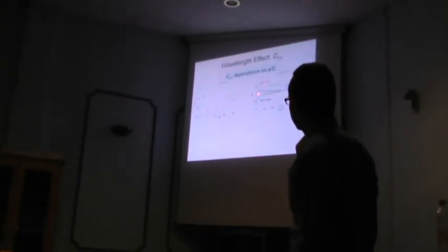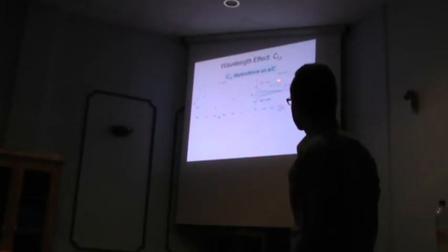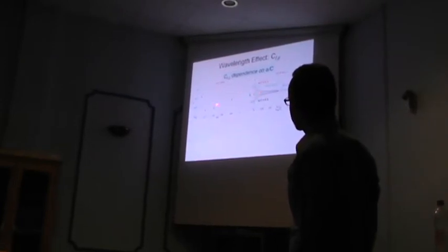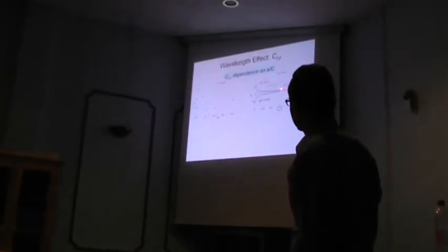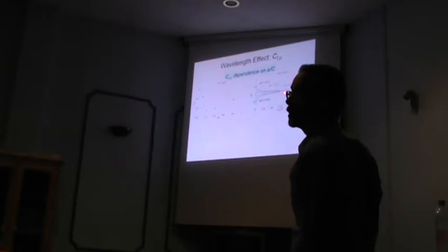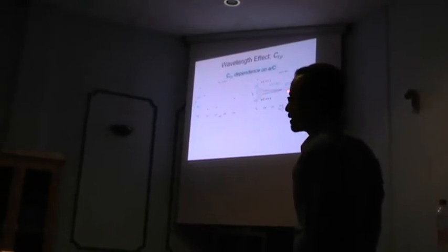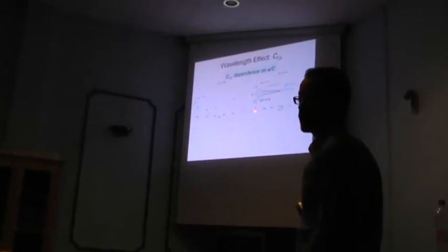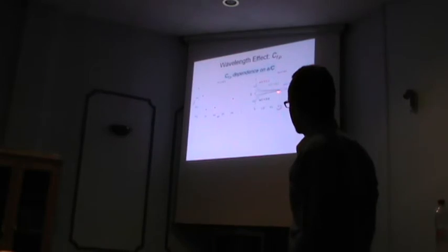For this small value, you have a profile that has this kind of distribution. You increase it to this one, which is the green. You can see how VRMS becomes stronger, and then it becomes wider, so that's larger drag. You increase it over here, then you go to this blue line, where now the peak actually goes down instead of going up. It's still becoming wider, but the peak level is becoming less, so the net effect is less drag. And finally, you get to this one, and it even goes down some more.